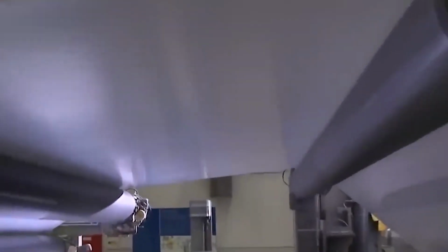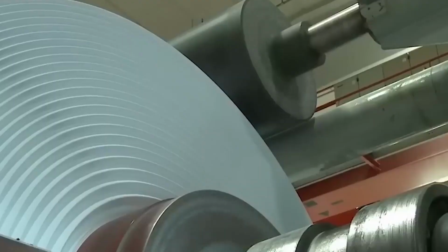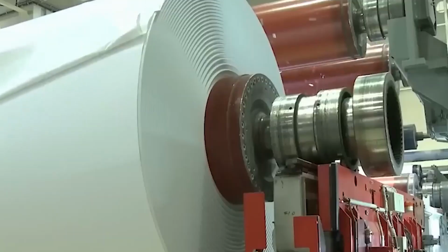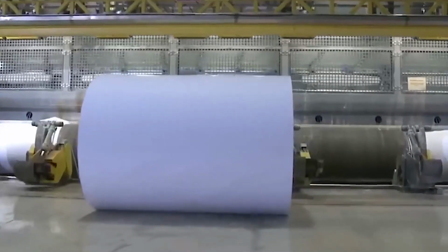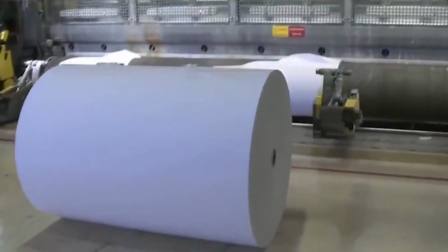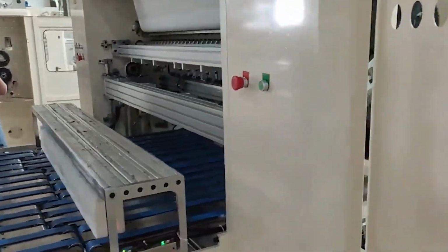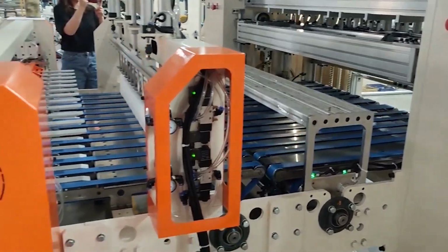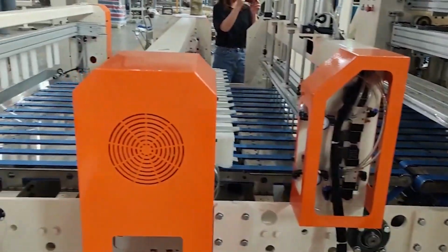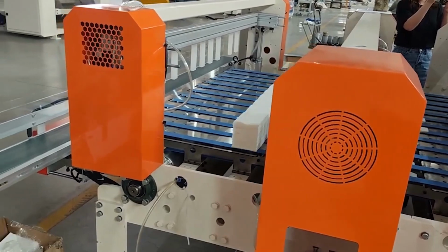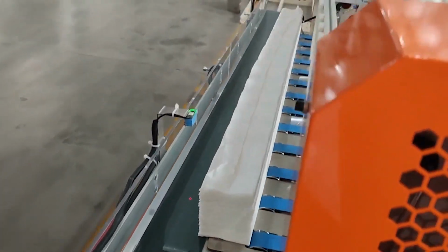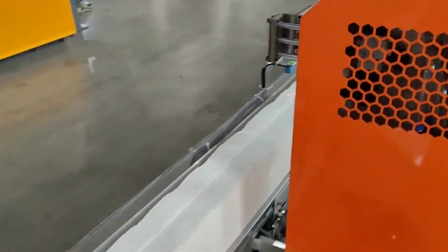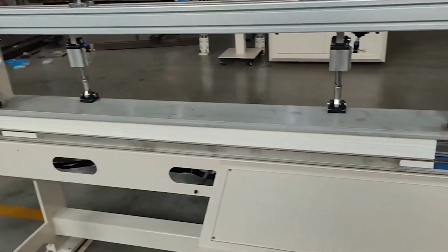This step typically takes place on a continuous wire mesh screen within a machine called the paper-making machine. The pulp slurry is poured onto the screen, and as water drains through it, the individual fibers begin to interlock and bond, gradually forming a wet sheet. This wet sheet is then passed through a pressing stage, where excess water is removed. The pressing not only aids in further consolidating the fibers, but also contributes to the density and thickness of the sheet. The formed sheet at this point contains a considerable amount of water, and it proceeds to the drying phase. Here it passes through a series of heated rollers that effectively remove the remaining water content, leaving the sheet dry and solid.